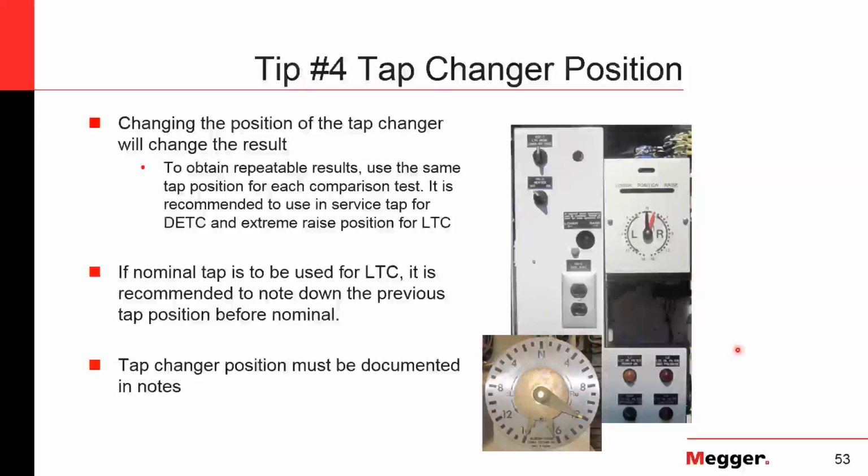The next thing, as I mentioned, once again, your connections will influence the result. So bad connections can actually vary the result too. If you look at this, this is actually the same transformer taken at two different times, and it's the same phase, it's the same measurement, X1 to X3. So we energized on the X1, measured on the X3, and everything else is open. But you'll see there's a large deviation here in the very high range frequencies.